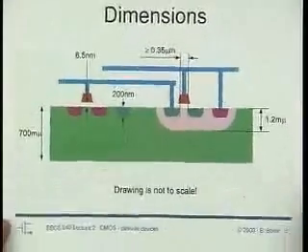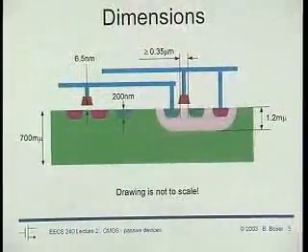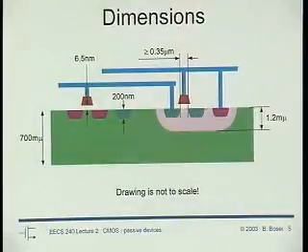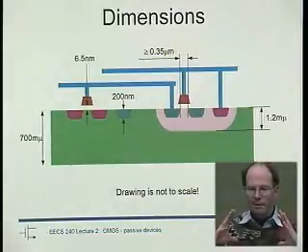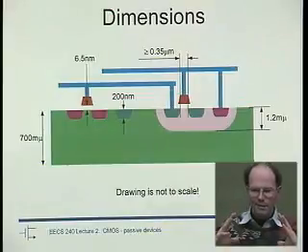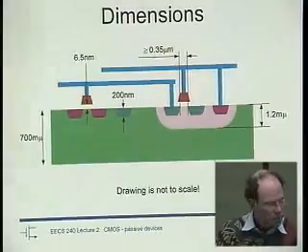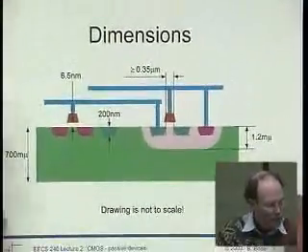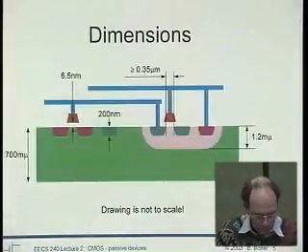Okay, so a little bit about dimensions. First of all, the wafer, 700 micron thick or so. That's primarily determined by mechanical stability. And in fact, wafer thickness is going up simply because the wafer diameter has been going up. If you have something 12-inch and you make it 300 micron, it's sort of like a piece of paper, but a little bit brittle and it's going to break. So they can be fairly thick. Really used for the circuits is only the top micron or so.